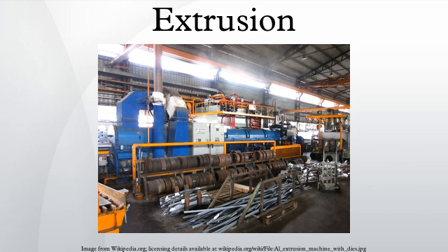The cooking process takes place within the extruder, where the product produces its own friction and heat due to the pressure generated. The main independent parameters during extrusion cooking are feed rate, particle size of the raw material, barrel temperature, screw speed and moisture content. The extruding process can induce both protein denaturation and starch gelatinization, depending on inputs and parameters.